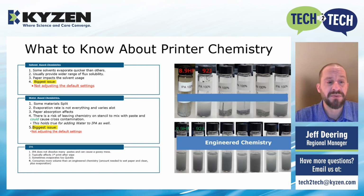And lastly, we have IPA. IPA does not dissolve many pastes and can cause a gooey mess. It typically affects the first print after a wipe. Sometimes it evaporates too quickly, which also can lead to it consuming more volume than an engineered chemistry when you take into account the amount needed to wet the paper and clean, plus the evaporation.